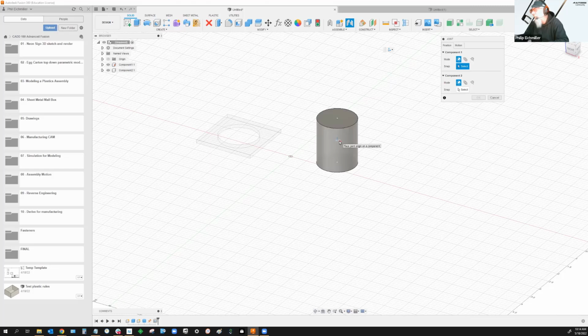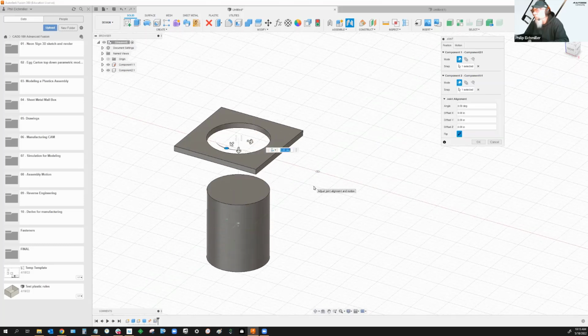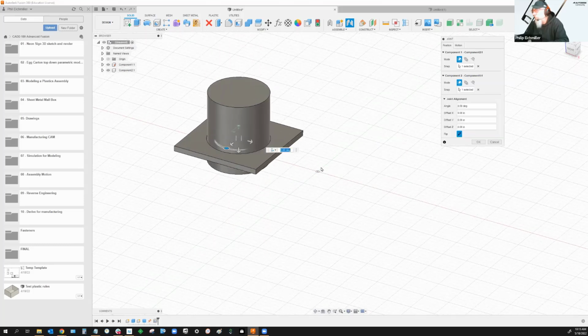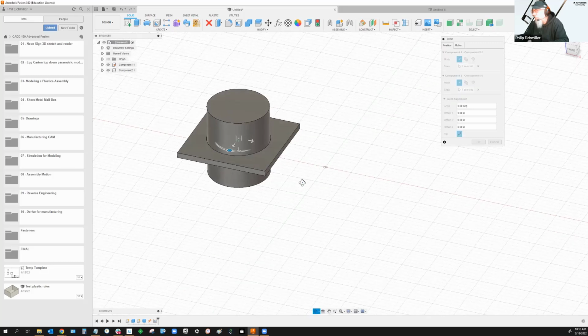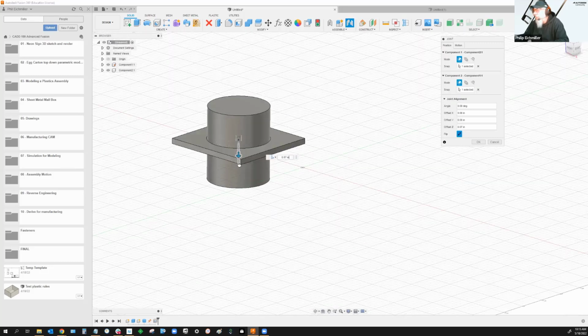How silly. Okay. So I pick a joint origin on the shaft, and then I pick a joint origin where that shaft might pass through something that's similar to a bushing. And you can pick where you want it to start. In other words, what's your 0, 0, 0 position? You can set that, and you can move it around at this point.